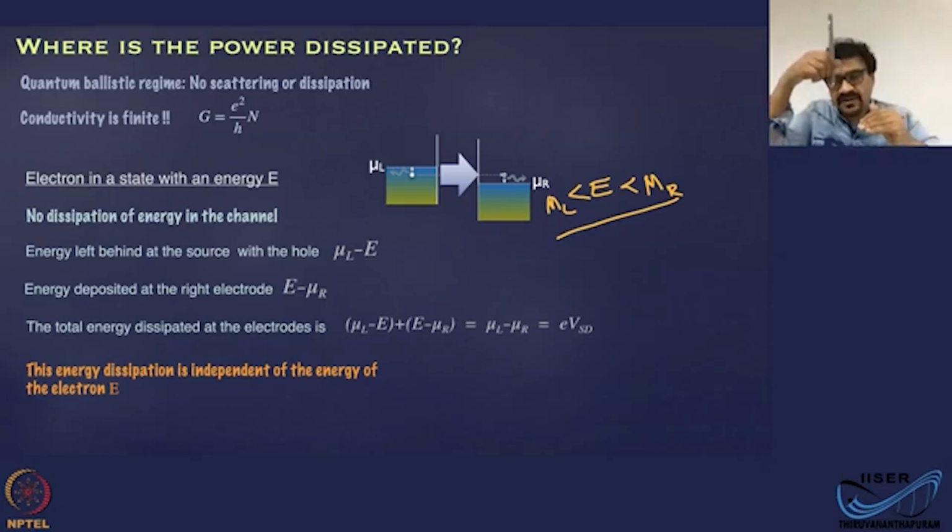The lowest energy for an electron is in the opposite direction, it's the bottom of the band. For the hole, it's the top of the band. They are just opposite. This is what is generally called the pebble analogy, where a hole is considered as a bubble, analogous to a bubble in water, which has the lowest energy when it is on the surface of the water, versus a pebble, a stone, which has the lowest energy when it is at the bottom of the tank.